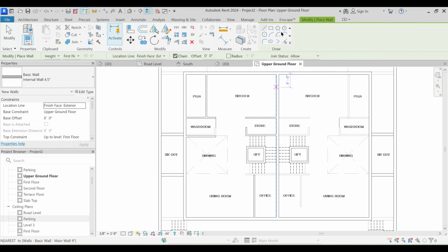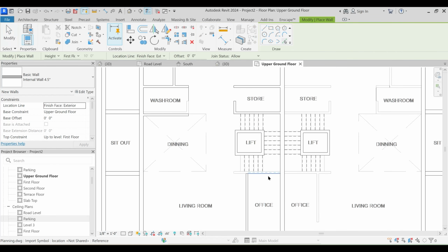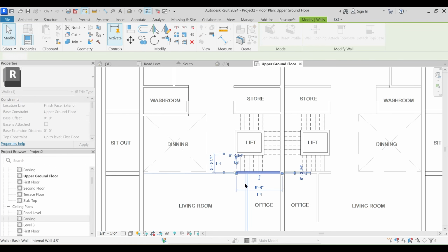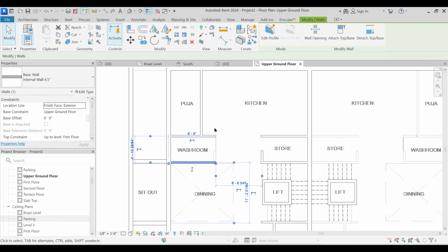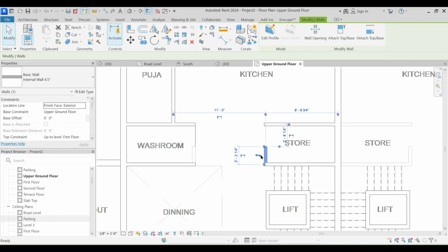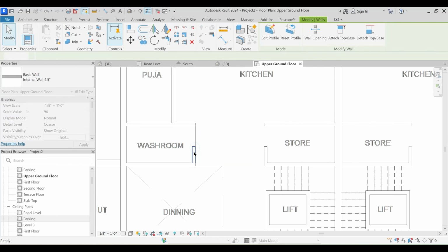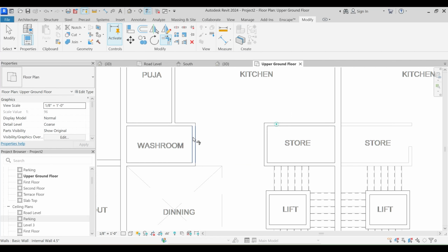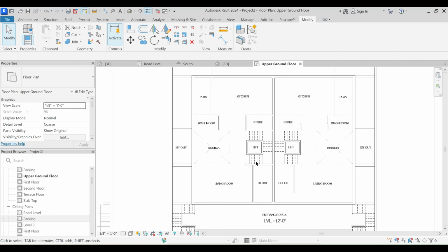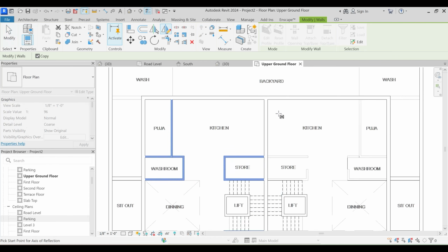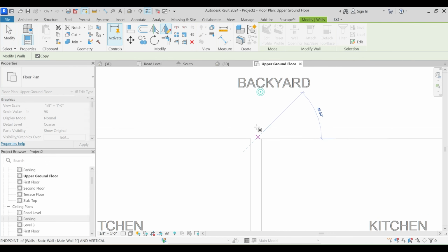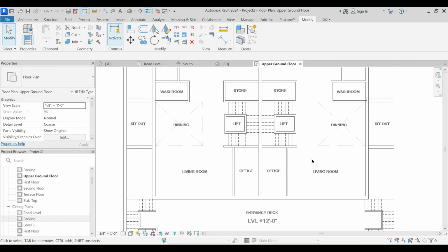Uh-oh, one I forgot. CS, pick lines, connecting this point to this point. Fine, and just flip this direction, copy it from this point to this point, TR, join this to this to this. Okay, and that's how we have created the internal walls. So let's just select this, and this. With this selected, just DM, that is mirror, pick this point and just mirror it.